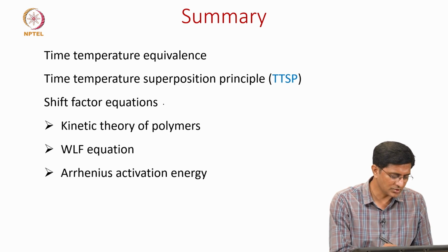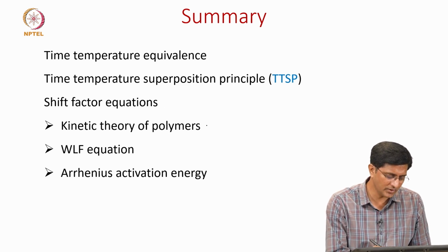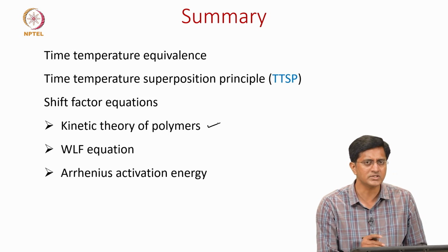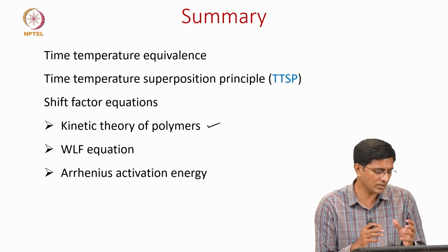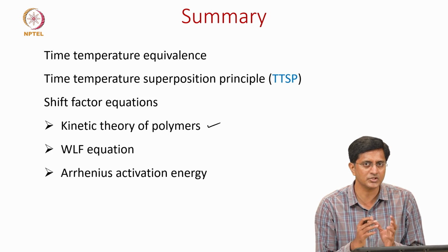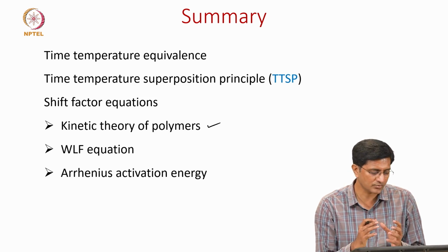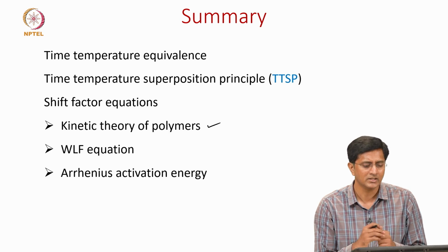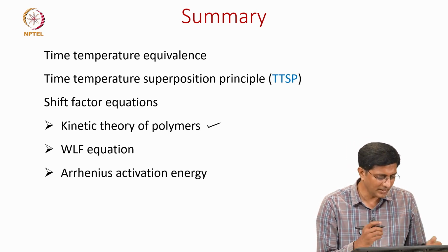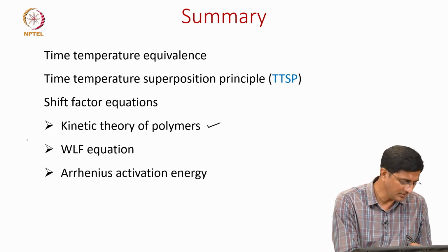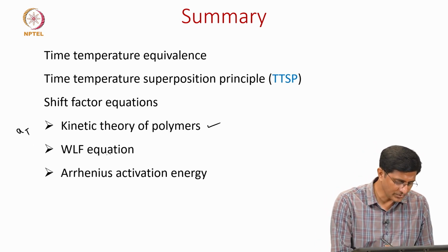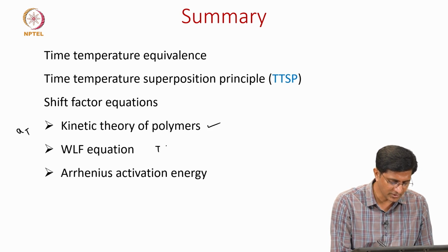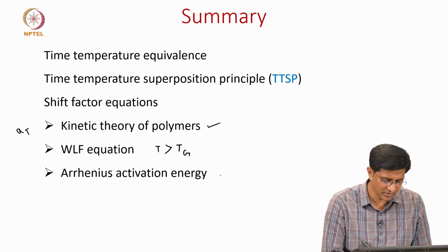So, we discussed these shift factor equations. First we discussed the kinetic theory of polymers. This is the theory on which the time-temperature superposition principle is based, and we also discussed that both of these are valid above Tg. But to get an equation for this shift factor AT, we use the WLF equation for temperatures above Tg, and we use the Arrhenius activation energy equation for temperatures less than Tg.